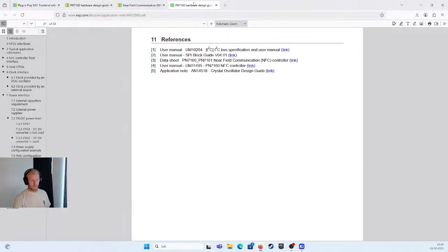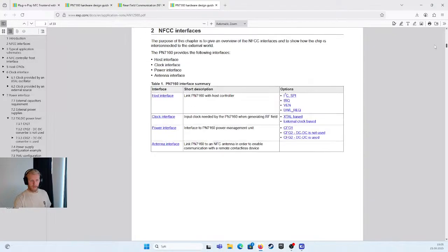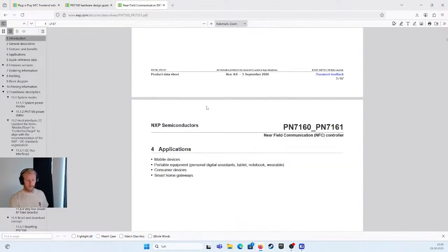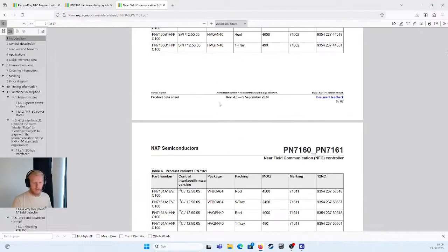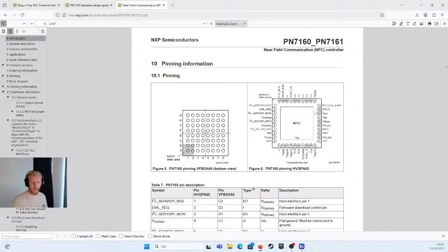And that makes sense, because if we go to the same one here, it's thermally enhanced because it has this VSS or ground thermal pad where we can put vias down to a ground layer and dissipate the heat.